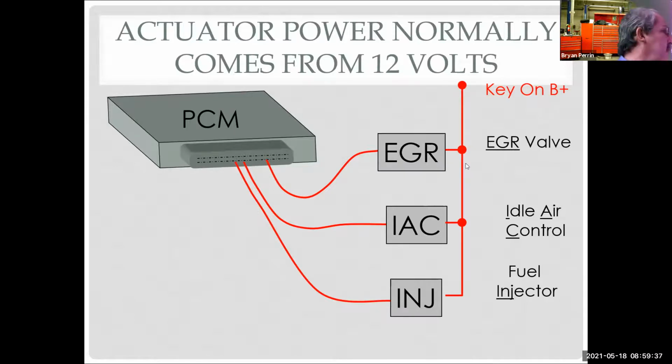If one wire goes to the battery like it does here, it has to be ground side controlled. But if this was chassis ground here, that would mean it'd have to be high side controlled. So the computer has to control the opposite of whatever the other wire is going to. And that wire is either going to go to power or ground, most likely power.